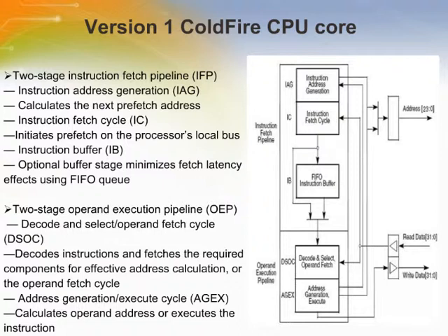There is no hardware support for MAC/eMAC and DIV instructions. It offers upward compatibility with other ColdFire CPUs version 2 through version 5. An integrated multi-master crossbar switch on the ColdFire system buses provides access to system resources by the CPU and Ethernet controller. The CPU configuration register has 1 bit for the control of the crossbar switch.